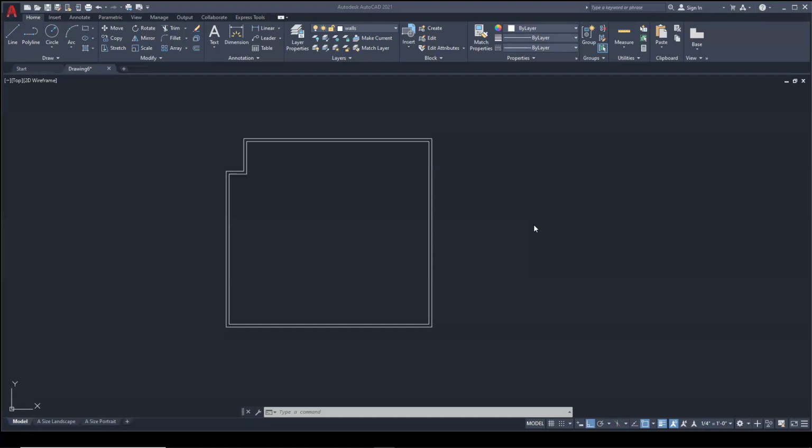Well, AutoCAD works in a very similar way, and those objects can be combined into blocks. We could, if we want, convert all of these line segments here, because each of these is a line segment. Right? When I click on them, one line segment is highlighted, and we could convert all of those to blocks. There's no reason to, and we don't need to, but we could if we wanted.